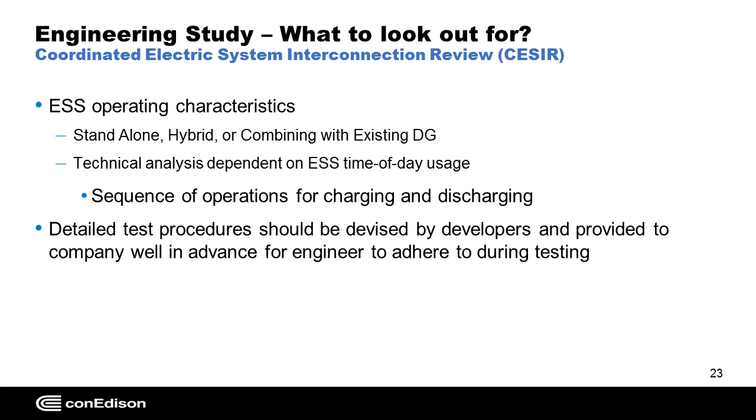For instance, if you kill the power to the inverter, or you kill the power to the site or simulate that, what does the inverter do? Does the inverter shut off? Also, when you bring the power back, does it take 5 minutes for the inverter to come back on? These are different steps that should be outlined in this procedure so that both parties are on the same page.